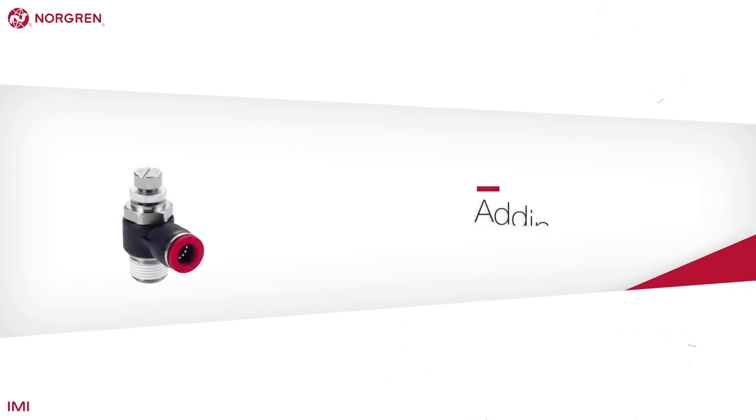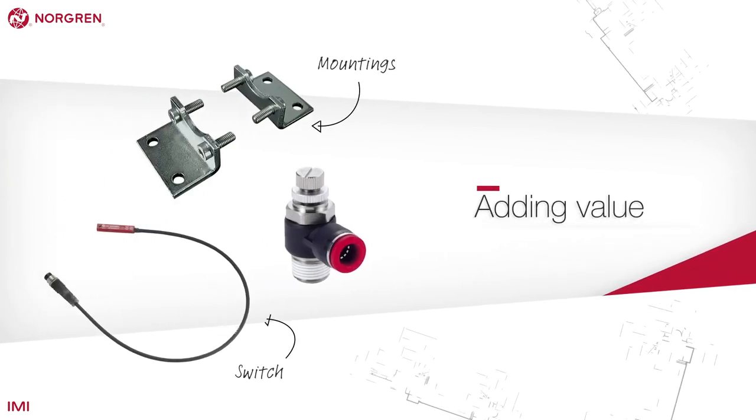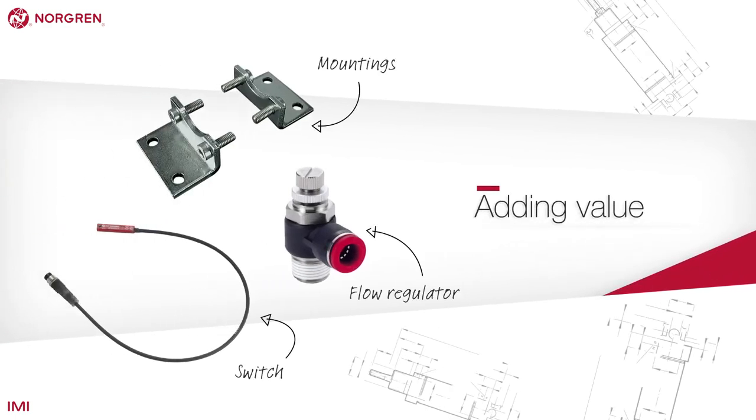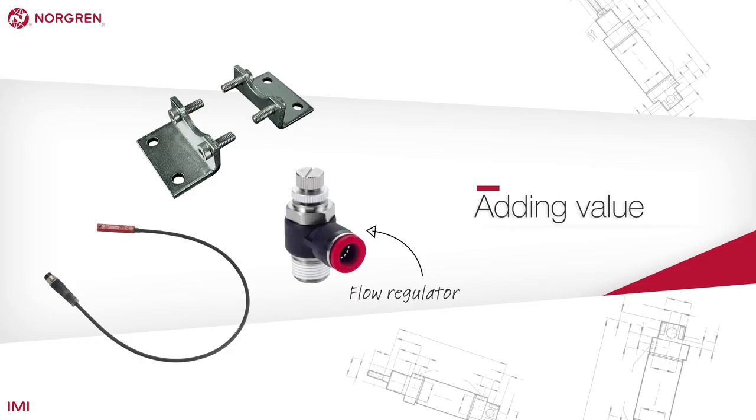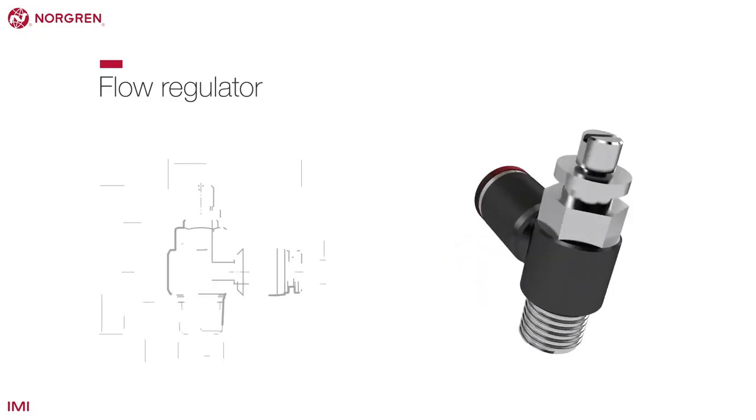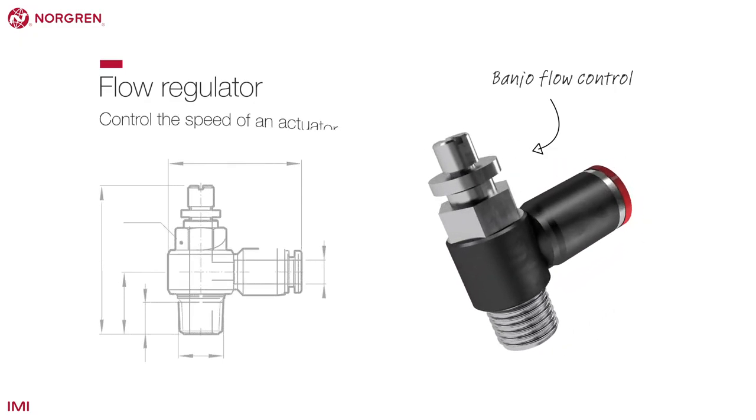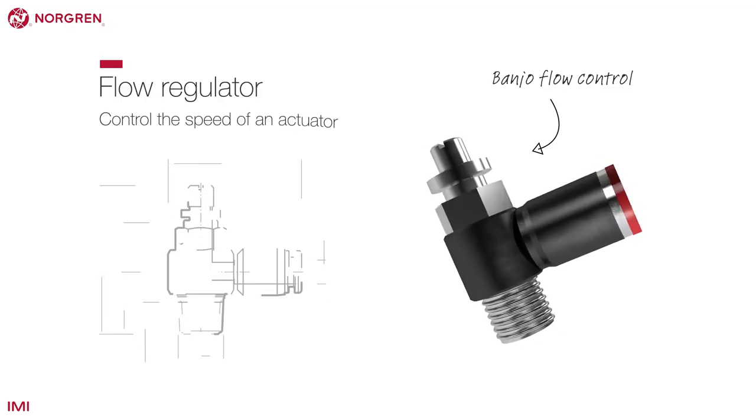Adding value. As well as mountings and switches, there are a number of other accessories available for Norgren actuators, including flow regulators. A flow regulator at the point of use is the best way to control the speed of the actuator. It's always worth considering what accessories will ensure the customer gets the most from their actuator. It's a great way to add value.